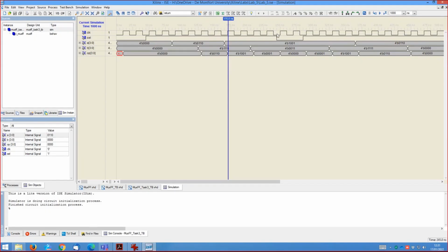You notice that at that point we are changing cell back to 0, which basically gives us an output of 0. Again, that only happens when the clock arrives, and it's only going to be reflected at the output when the clock arrives, once cell has been changed to 1 and we start ANDing again. So that works exactly as intended, and that's pretty much what we had to do today.